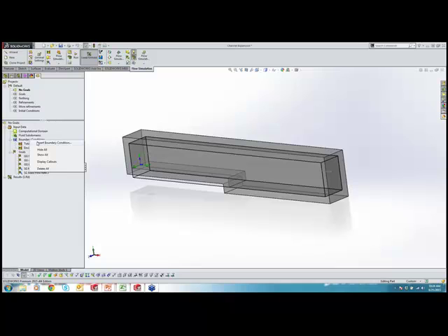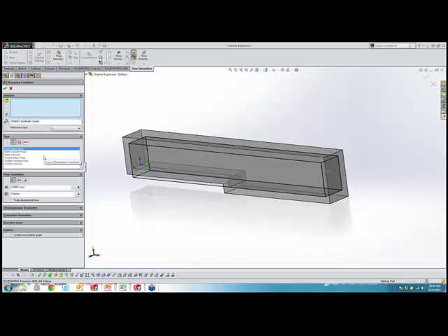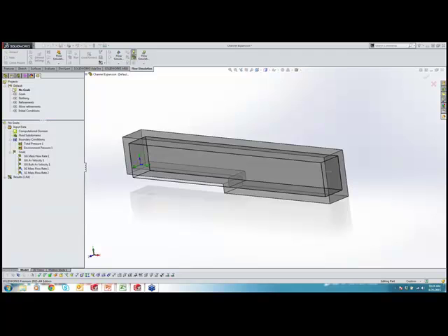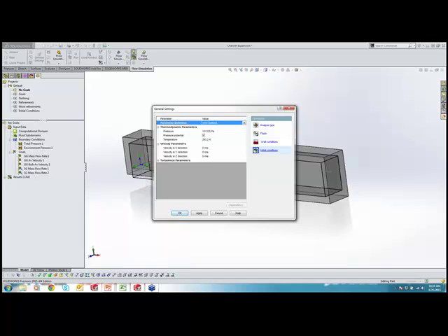For your boundary conditions, you can specify all these mass flows, volume flows, anything like that. Also specify them as pressures. And if you want to improve those in the initial setup, general settings, initial conditions, you can also specify a global pressure. So if you're expecting flow in the pipe to be somewhere around 2 atmospheres as average, you could set it that way, and then it would propagate the pressure away from 2 as opposed to trying to build up from 1 or wherever you're at.